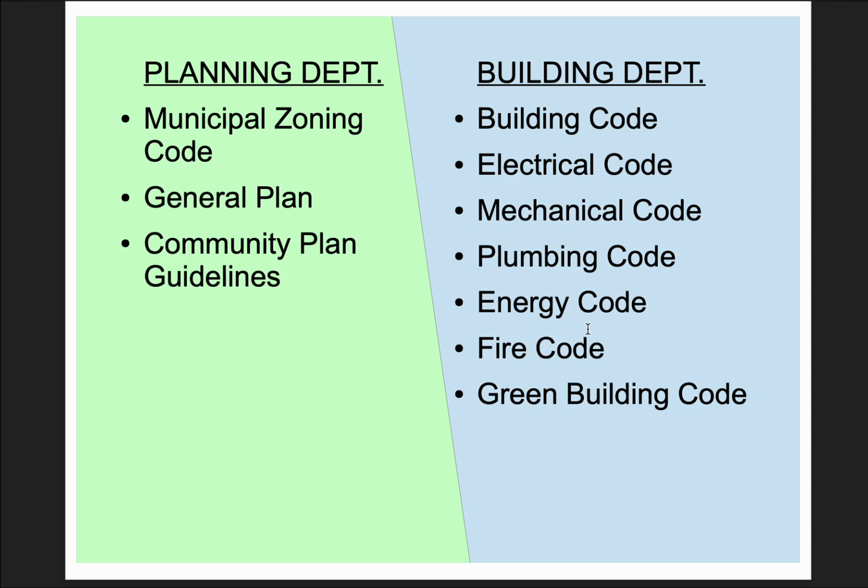As an architect, the fire code is something that's typically embedded with the building code, where type of construction and details are going to be established, and they will have a UL approval code that would say that this kind of construction is a 2 hour rated wall, a 4 hour rated wall, in case of fire. If you needed a hallway as an emergency exit, that hallway should be 2 hours or 4 hours, and it might require 2 layers of chipboard, or maybe concrete, before it can be approved.